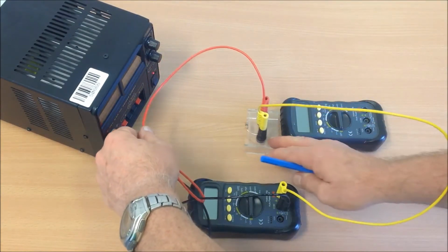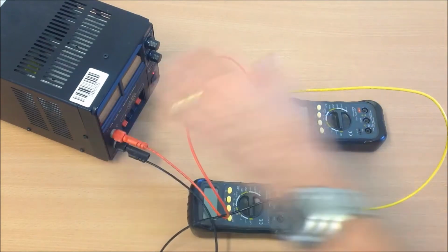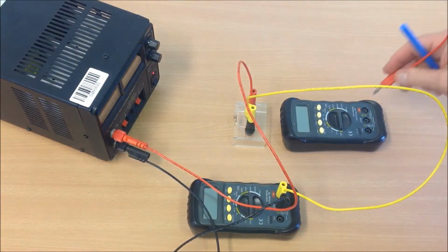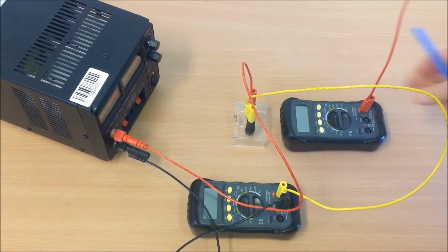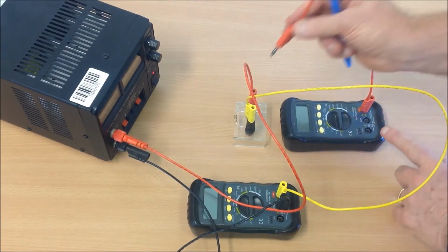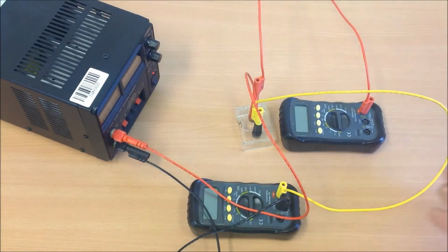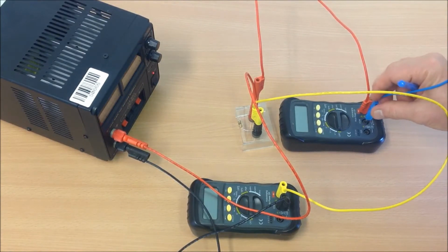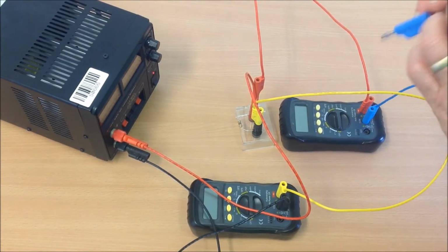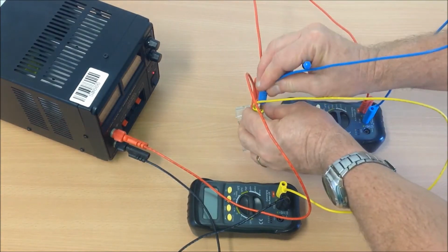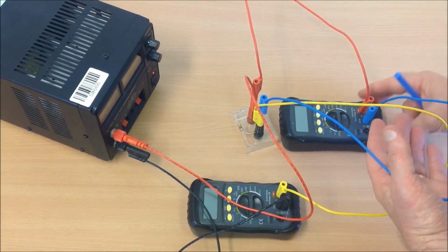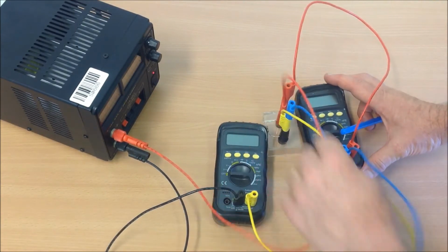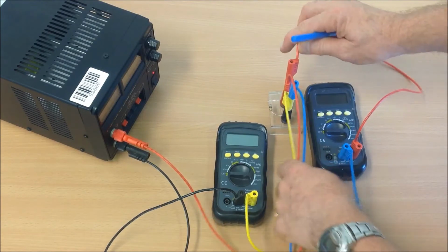Now the next thing we have to do is to measure the voltage across the resistor. And to do that we need to connect the digital multimeter we'll use as a voltmeter, again positive side of the voltmeter to the positive side of the resistor, and the negative side of the multimeter from the common input to the negative side of the resistor. So now we're measuring voltage across that. We'll simply turn these around now to make them a little bit easier to read. Try and get the wires a bit out of the way.